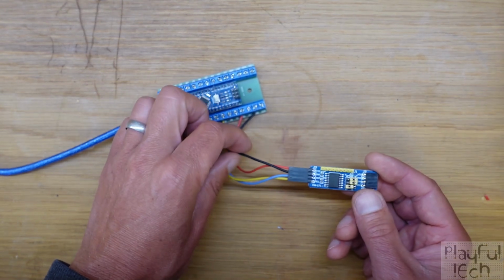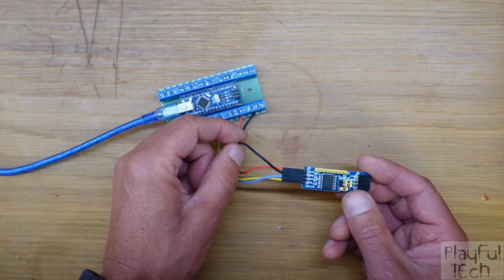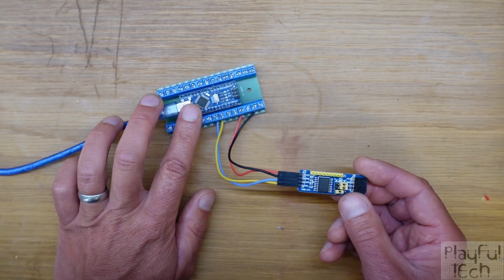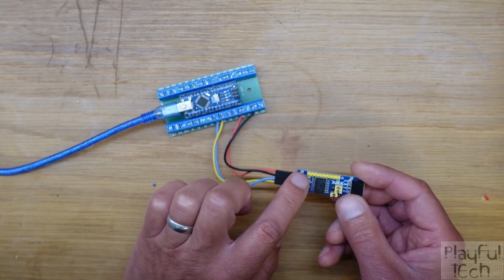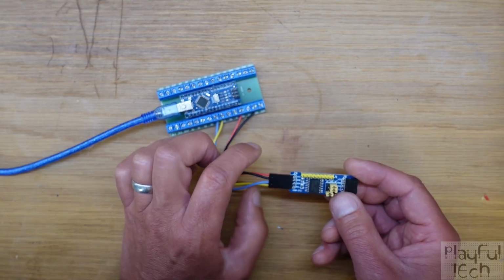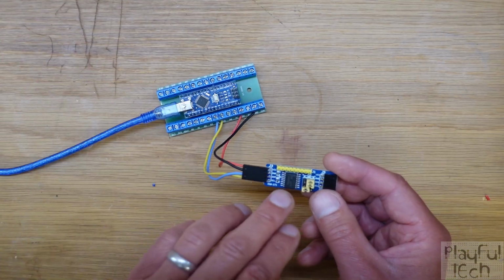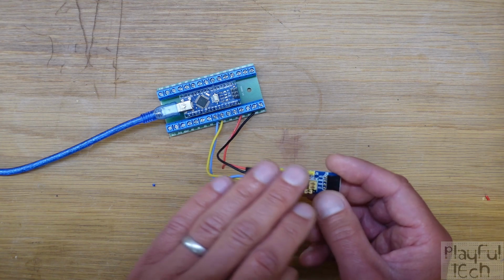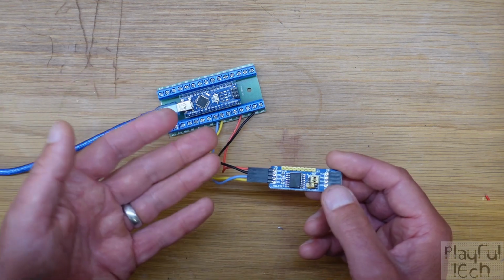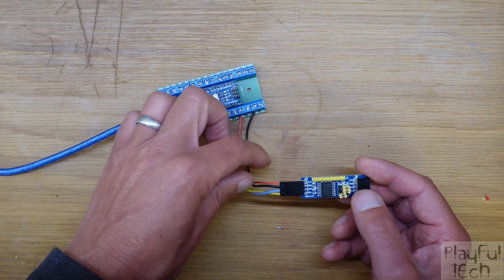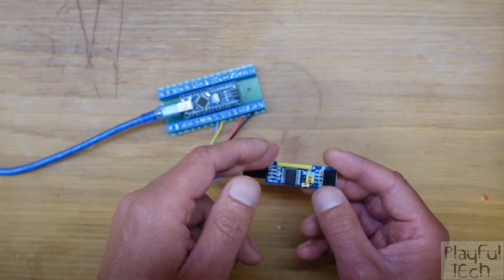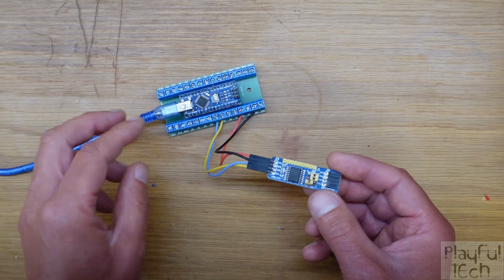We've connected the ground line together, which gives it that common low reference, and because we're using an Arduino Nano, we've connected the VCC to 5 volts. So that defines the voltage that the chip here uses to set a high signal on any of these pins. If we were using a 3.3 volt logic device, we could have supplied 3.3 volts on this line instead, and then high would only have been 3.3 volts. Neat, huh?